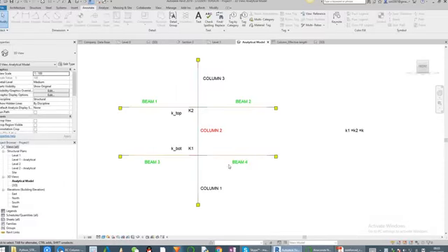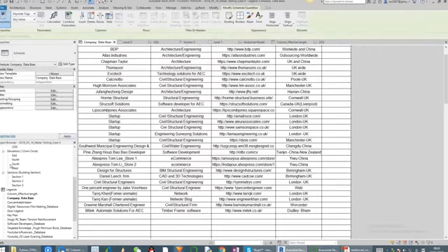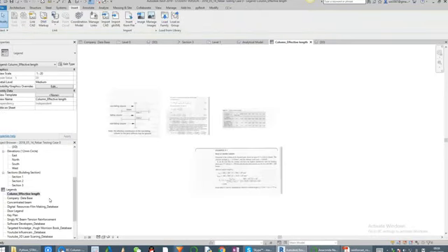Let's go to Revit for a while. This is the column. I want to calculate the effective length of this column number 2. Obviously, before that, I need to know the values of K1 and K2, which in the code are also called K sub bottom and K sub top. So let's see what those values are. Let me go to the Revit database, column height.